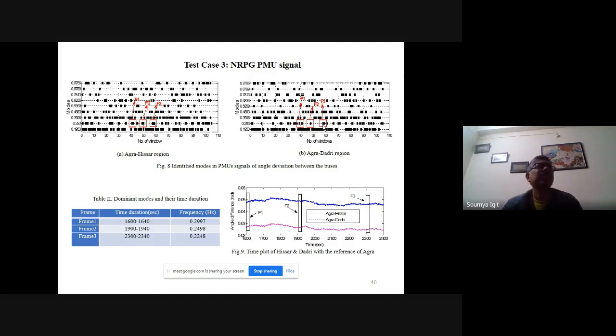Several factors means, for instance, your intelligent relay, your transducer error, your attenuation, phase, amplitudes, your transportation lag. But that should have a replication of the original system within a tolerable band.